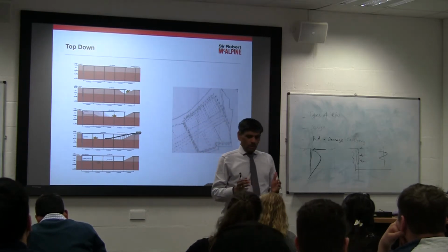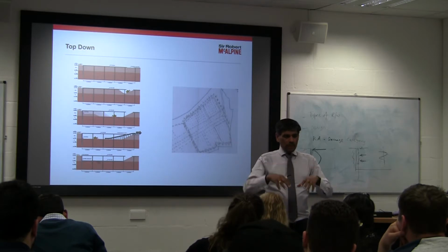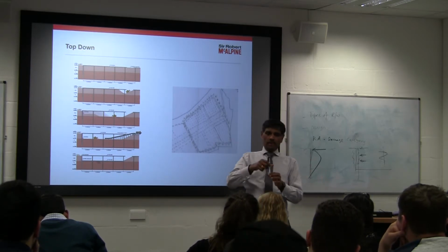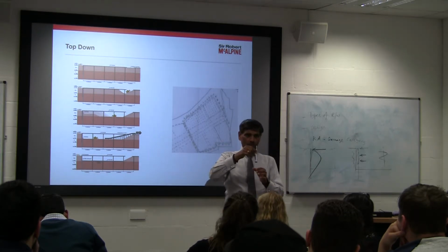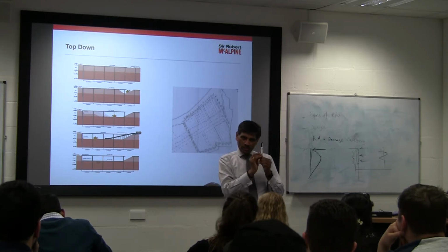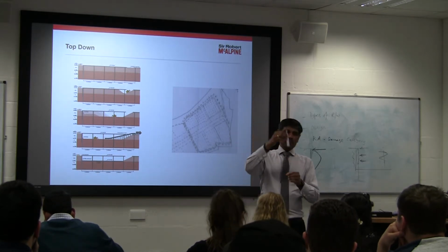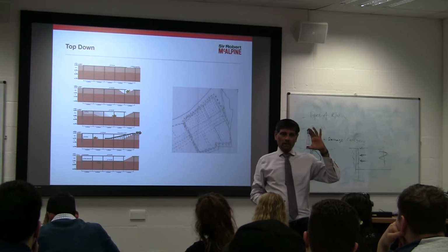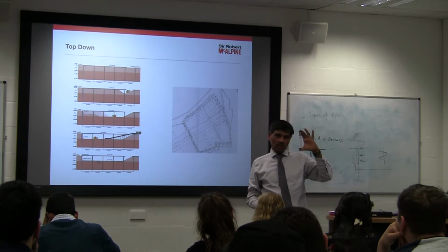So when you do the piling, you got a temporary casing. In the temporary casing, when you drop the plunge column, it has got a connection to the slabs. Yeah? So the plunge column will have shear studs. So this is the plunge column that is going into the pile. That is fabricated to the accurate levels. Yeah? Because this is steel, we can control it.